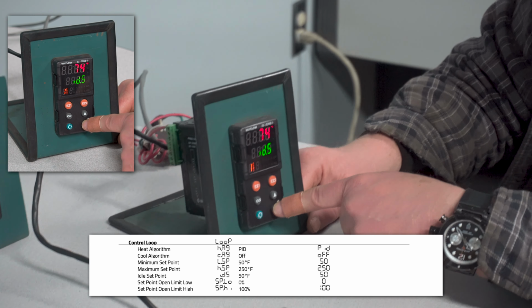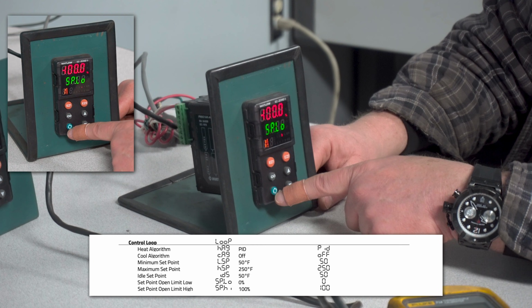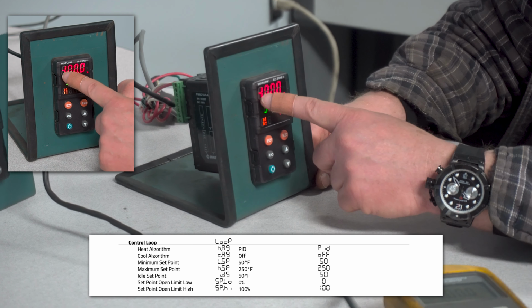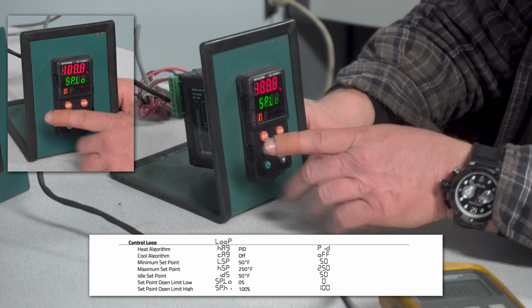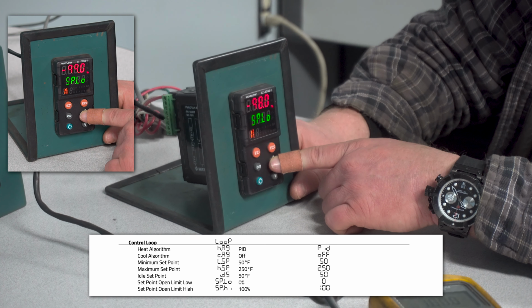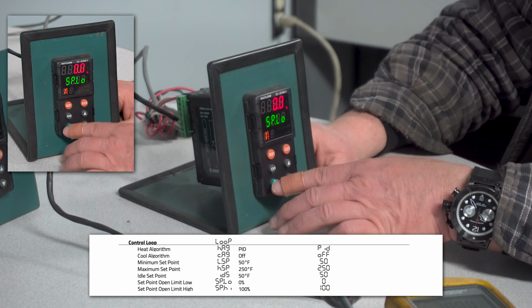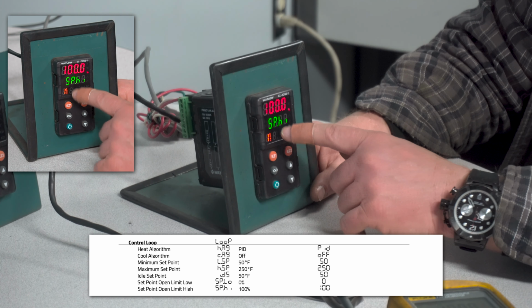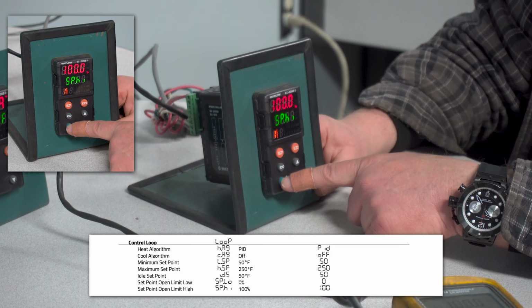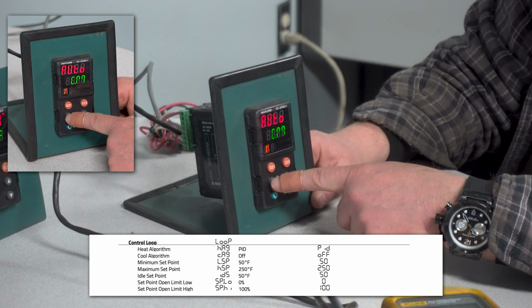I'm going to make our idle set point 70 just for convenience. Our set point low is minus 100%, but since this doesn't have cooling, we're going to change this to 0. Hit the cycle button again. Our set point high is 100%. And we're back to the beginning.